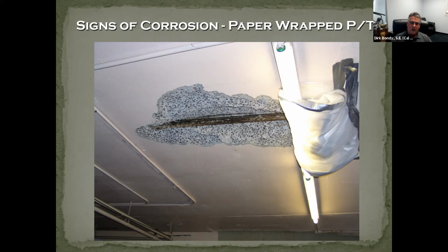Now, what you're looking at back in the 70s, the really popular way of post-tensioning was to wrap it in paper. They weren't thinking about the extruded plastic that we have today. They weren't thinking about long-term corrosion. Post-tensioning was relatively new in the 60s and 70s, at least in the United States. And so they wrapped it in paper, greased it, and the post-tensioning pre-stressing steel needed to move while it got stressed. After that, they weren't thinking long-term about it.